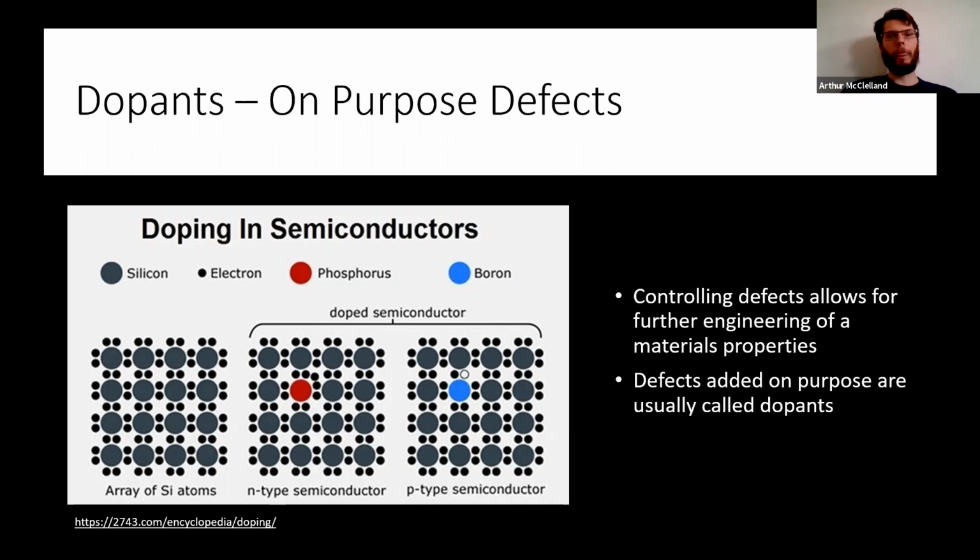So it's N-type. If we put in a boron atom where a silicon should be, boron has one fewer electron. So we have a hole here. We are missing an electron. This effectively ends up having a positive charge, so we call it P-type. This hole can jump around. You could think of the electron jumping here, or you could think of the hole jumping there and the electron jumping there, and then the hole can sort of jump around.